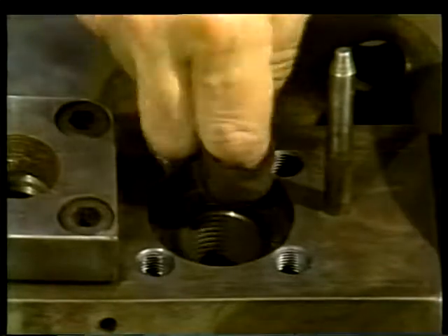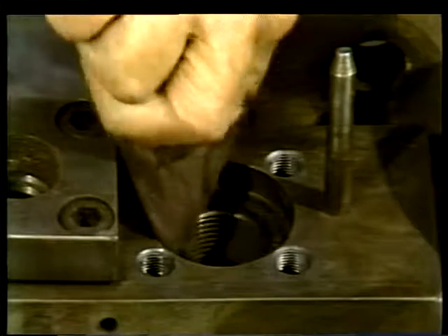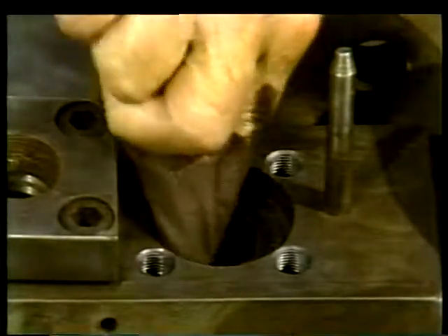Clean the gauge body gasket seating surface with a rag. A brass wire brush can be used if necessary. Do not use a steel brush because steel will damage the seating surface. Do not scratch or gouge the seating surfaces on either the gauge body or the cover plate. Look for scratches while you clean the parts.